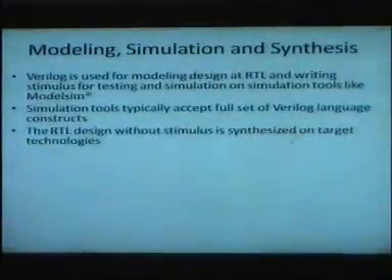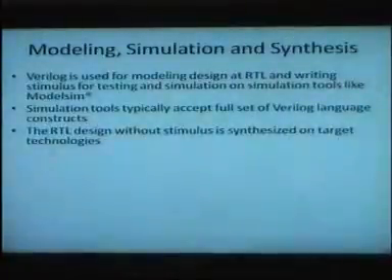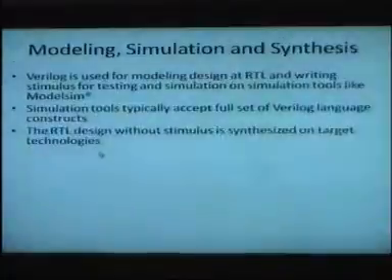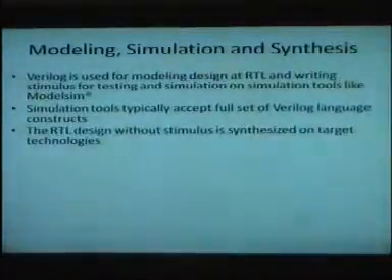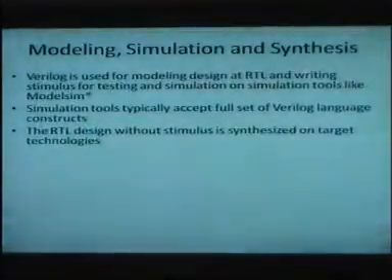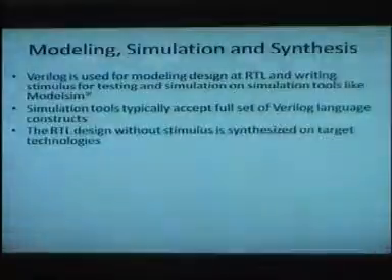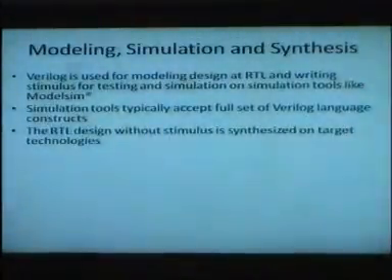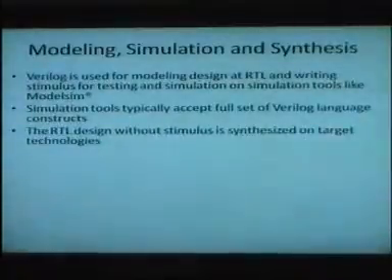So Verilog, as it says, the whole entire Verilog is very rich. They are adding more and more functionality. But RTL design is very simple Verilog, because synthesis tools will only understand a little Verilog, and they translate it into hardware. And anything you write outside that little Verilog, they'll get confused. They'll say this is non-RTL. I will not translate it into hardware.